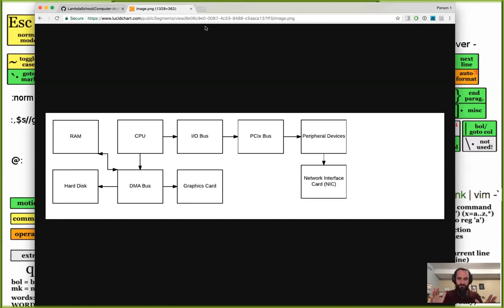So anyway, we figured out that there's 256 megabytes of data required to display my 4K display. And what happens is my video card has its own copy of that memory, and it displays it. It's got its own internal clock cycle that's worked out over the HDMI bus that's plugged into my TV, and the TV has a CPU on the other side of the HDMI bus to load the data. And every clock cycle, if there's a change in the memory that makes up my computer display, my video card sends that over to the TV, and it changes a pixel.